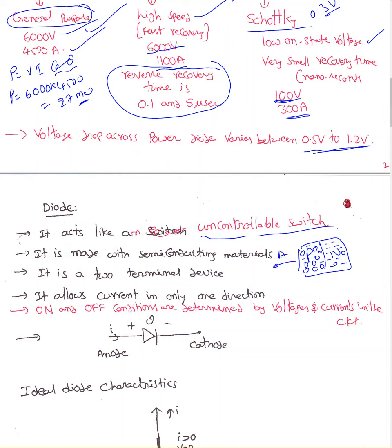So this is the anode, that's the cathode. When I apply forward bias, a higher voltage to the anode, this side is positive. Holes, in reality, don't have any charge, but I can take them as positive charge. So positive charges repel, and when I apply negative to the n-type material, they repel, so this junction is going to break down. There is a current flow in that circuit. That's called forward bias.